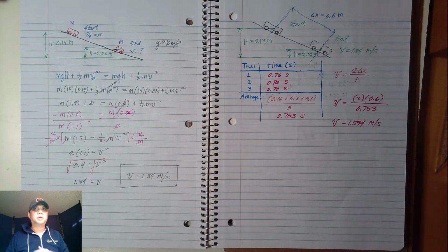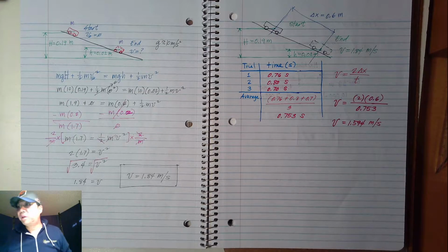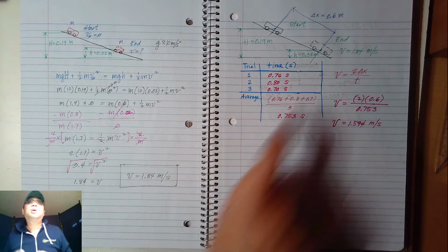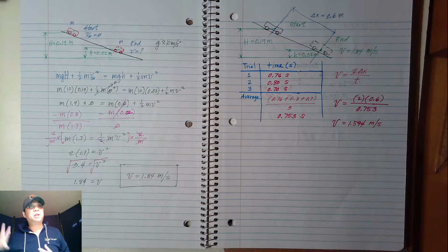There are other factors, but most of the time we will consider friction as the culprit. Okay? Because of the wheels, maybe they're not properly lubricated, and it's starting to eat up metal to metal, and it doesn't have bearings, but instead just an axle or a shaft that is placed in a hole with the wheels attached to it. Also, maybe the ramp is a little bit slippery, so it slips. So this time the desired friction was not enough to keep traction.